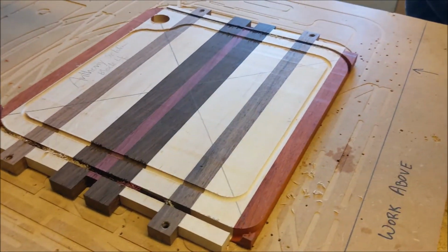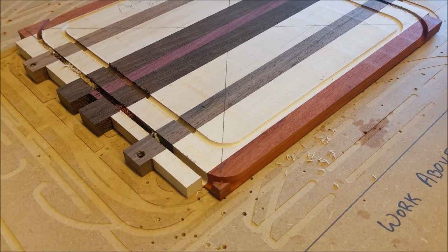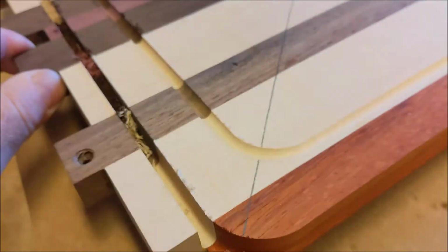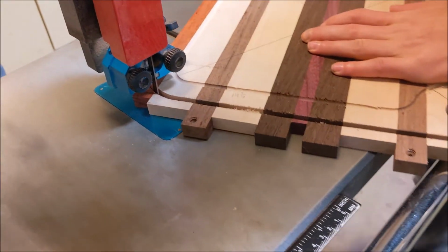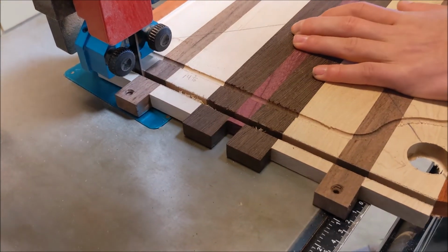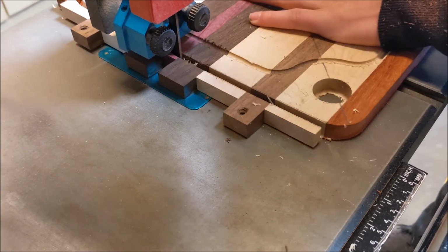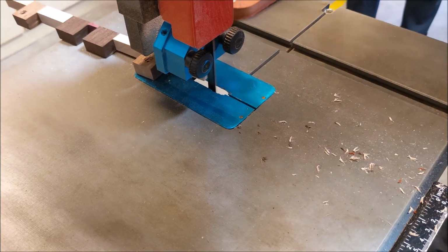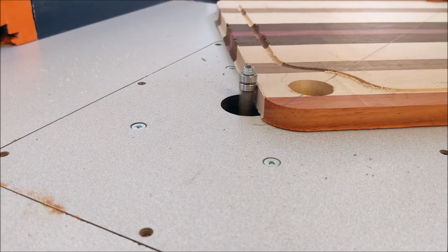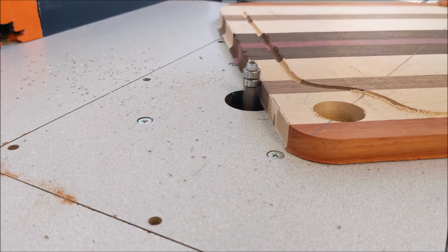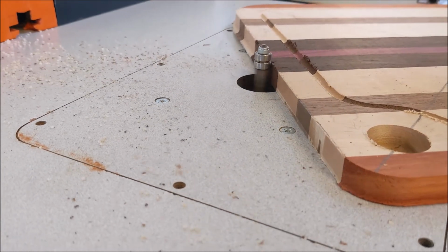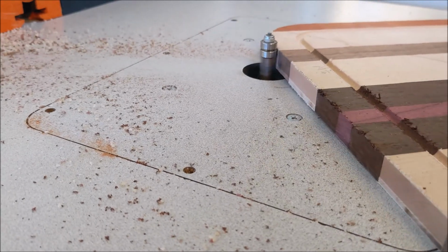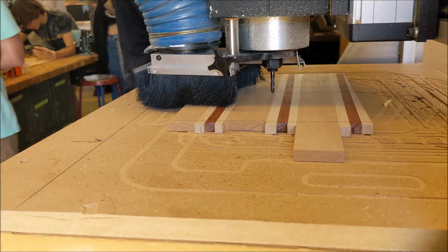So here we are pulling the screws off, and it didn't actually pop all the way up away from the holding points. So what we do from here is we're going to go over to the bandsaw, and we're just going to cut off that excess, being really careful not to damage the board. And then once that excess is cut off, there's still a little bit left, also because we used a ball end mill. So we're going to go over to the flush trim router bit table, and then just flush trim that last little bit of wood on there, and then it'll be a perfect part. A little bit of sanding, it'll look like new.